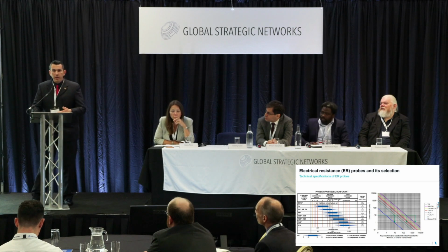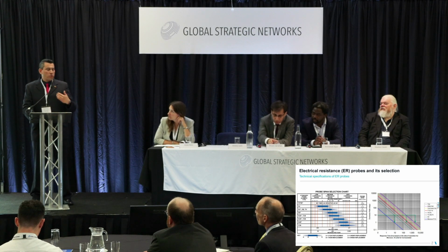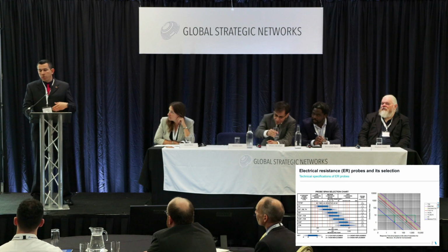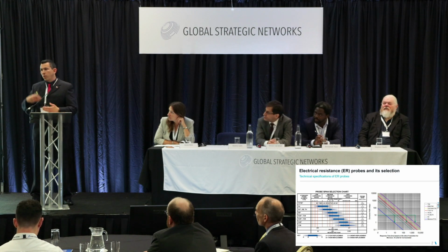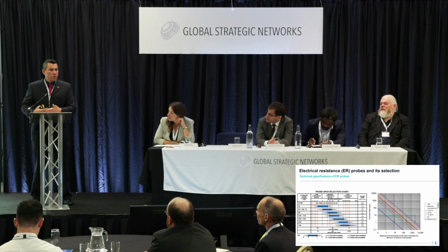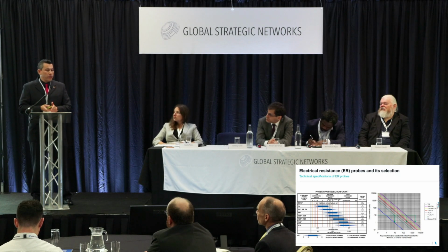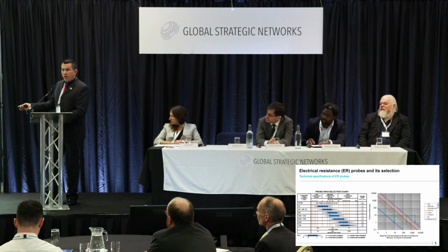If you're in a refinery and you want to make sure that your feed is not containing high levels of chloride, or your desalter process is not working properly, or the top of the distillation unit is not working properly, or the corrosion inhibitor is not working properly, you want to have a corrosion probe that has the shortest response time.